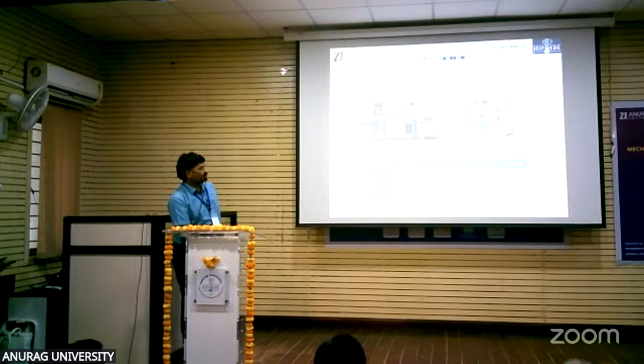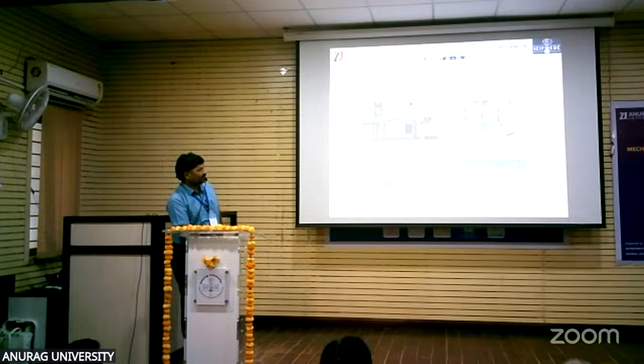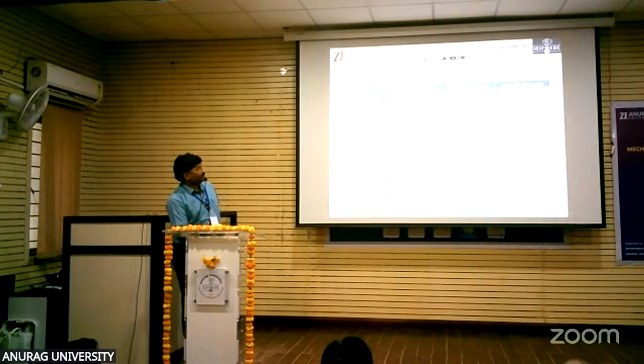For the design, I used the Taguchi technique with 4 levels. Pressure is 2.5 bar to 4 bar, weld time is 2 seconds to 3.5 seconds, and amplitude is 30 micrometers to 60 micrometers. I took the Taguchi L16 orthogonal array. These are the L16 orthogonal array, and I set up the experiments.